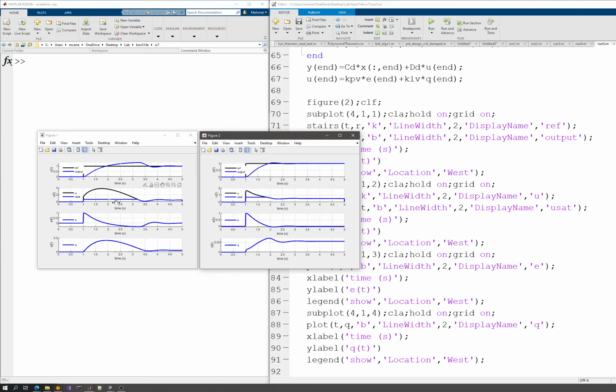Keep in mind that if an integrator has an input that is constant, it will generate a ramp function, which is basically an unstable signal, because if you look at the final value theorem, the ramp function will tend to infinity. Basically, if t is tending to infinity, then the output of an integrator with constant input will tend to infinity, and this is not stable.